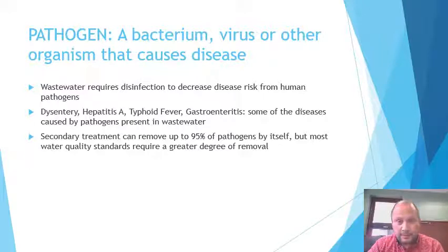Chlorine is less effective in cold weather. Also, in the months of December and January, water contact recreation is pretty unlikely. Here in Perrysburg, we use that time to maintain our system. Now that we switched from chlorine to UV disinfection, I wouldn't be surprised at some point to have to disinfect 12 months out of the year. But currently, 10 months, beginning at the end of February. Actually, March 1st is when we have to start, and we are done November 30th.